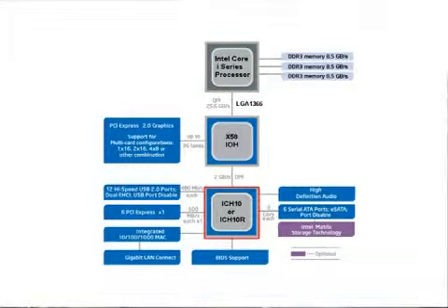Now the south bridge component in motherboards has been pretty steady in its functions for many years now. We have connections to things like audio. We have all of our hard disk, our serial ATA or parallel ATA connections in some cases. We have USB. This particular chipset supports 12 USB ports. We have PCI Express bus slots. These are the slots other than video that you would plug cards into. We have things like Ethernet controllers, the motherboard ROM. All of those devices are connected directly to the south bridge.